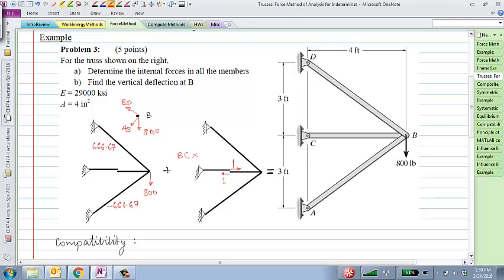It's a symmetric 3, 4, 5 triangle, both above and down. So this is the force that you should get. That's the response of the actual structure. And note that both of those legs would be 0 force members because there is a cut there.